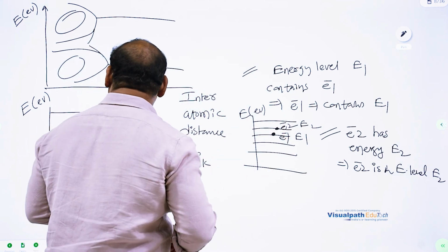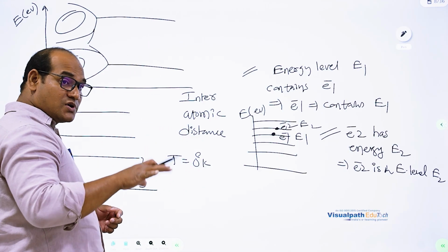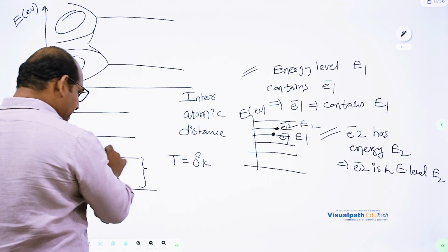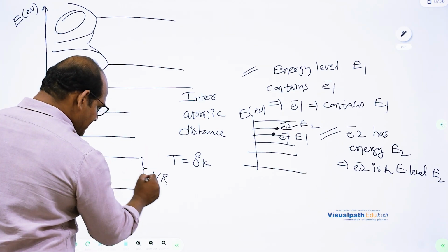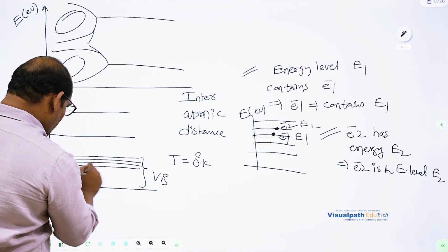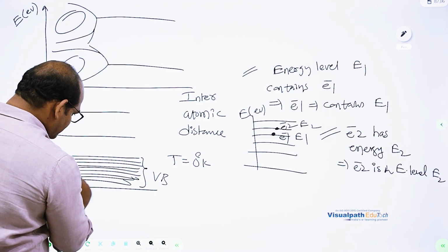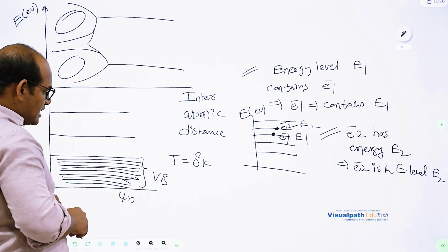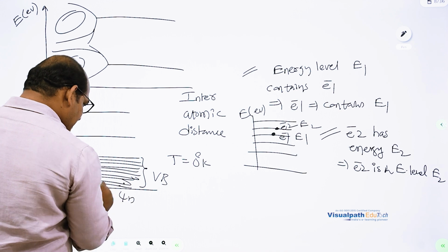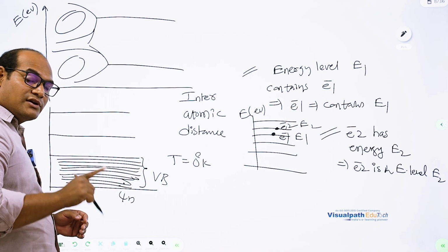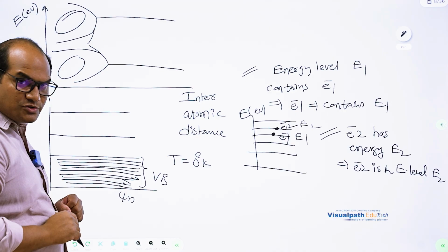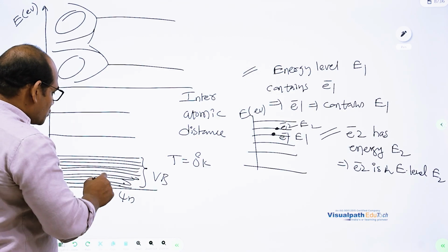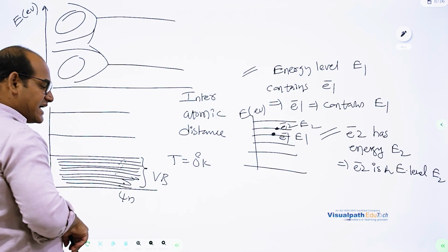Okay, now coming again to this particular case, here n silicon atoms you have taken, so that 4n valency electrons are possible. All those 4n valency electrons are available in the valency band. This is called a group of energy levels. So all these are 4n energy levels available here. So electrons are available. One electron is here, another electron is here, another electron is here. In one energy level, only one electron can be possible according to Pauli's exclusion principle. No two electrons can have the same amount of energy, that is nothing but this one only. Okay. So here electrons are available in different energy levels like this.